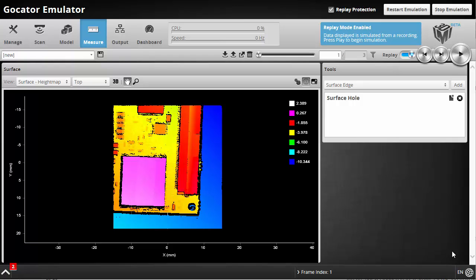The 4.6 firmware release simplifies the work of extracting and measuring geometric features in your scan results. Tools in previous firmware releases only ever produced scalar measurements. Now with the 4.6 release, tools can also output features, specifically points and lines. These features can then be taken as inputs into other tools to easily perform measurements between the features. Most tools now produce features.